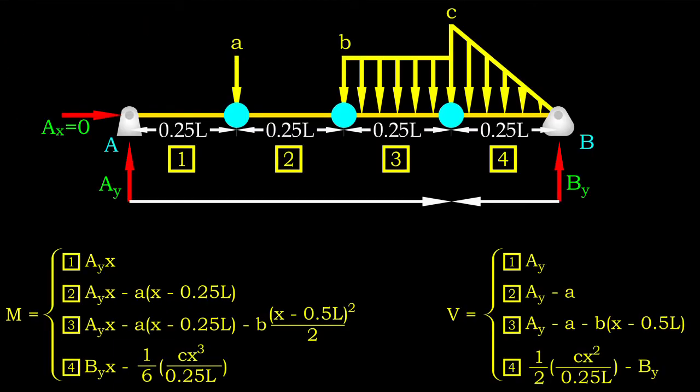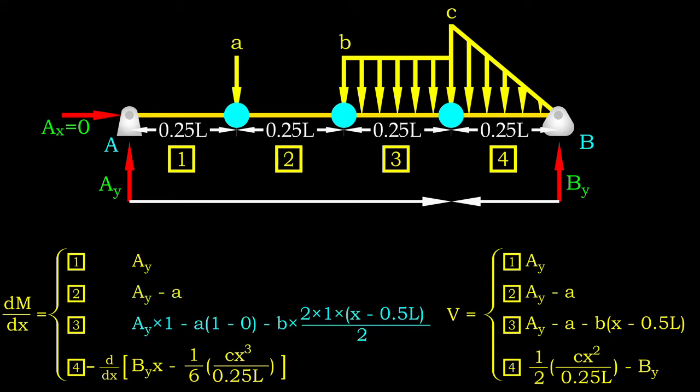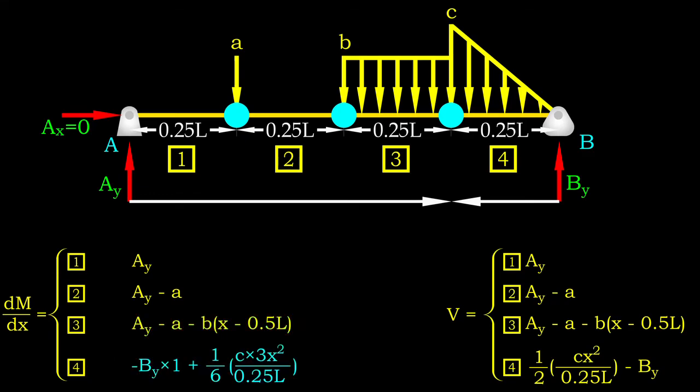Now, you might have noticed that we can obtain shear force function by differentiating the bending moment function with respect to x. Therefore, given a non-constant shear force function, the bending moment will be the most critical at the point where shear force is 0. These internal force functions and correlation are very useful during construction of shear force and bending moment diagrams. In next video, we will demonstrate how to develop diagrams using these functions.